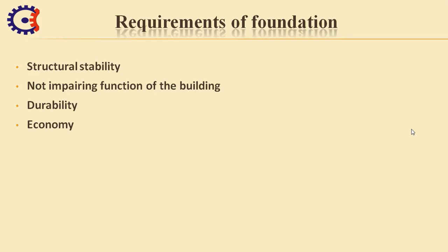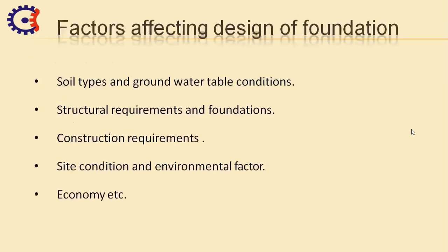Differential settlement can be avoided by having a rigid base for the foundation. The issues are more pronounced in areas where the superimposed loads are not uniform in nature. Based on the soil and area, it is recommended to have a deeper foundation so that it can guard against any form of damage or distress. These are mainly caused by shrinkage and swelling because of temperature changes. The location of the foundation chosen must be in an area not affected or influenced by future works.